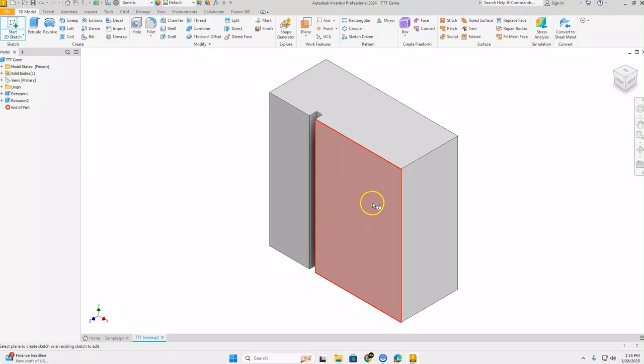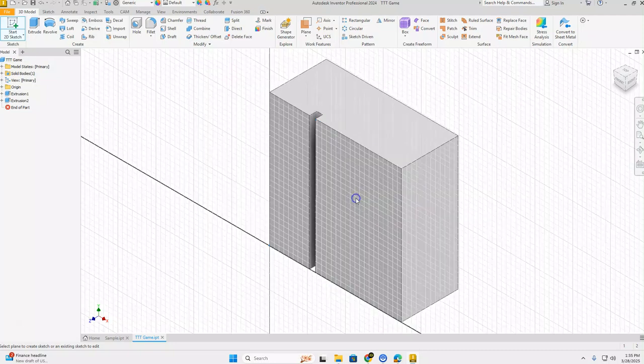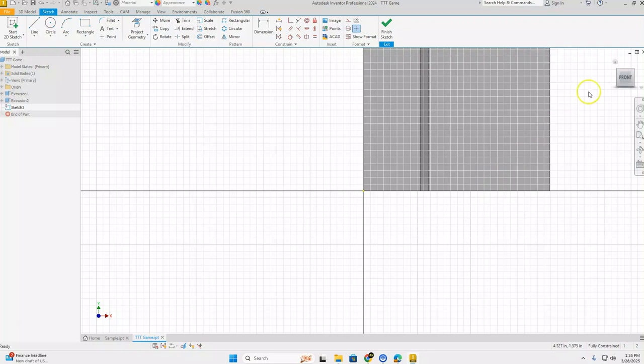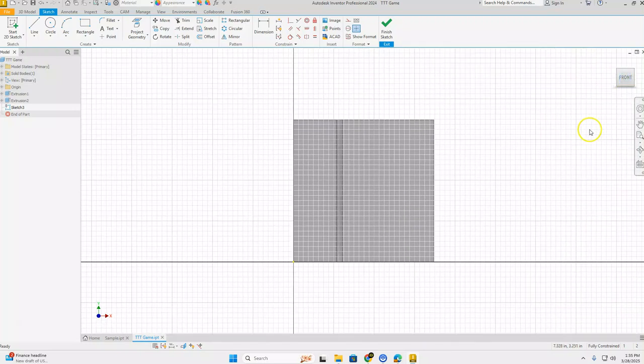So once this large side is highlighted red, click to place it. And then of course we're going to click front in our world view cube in order to center it on our screen. And let's go get our rectangle tool again, and we're going to start way up off our part. We're going to click, let go of the mouse button, and we're going to stretch out another rectangle so that it's off of the part at the top and off of our part at the bottom.